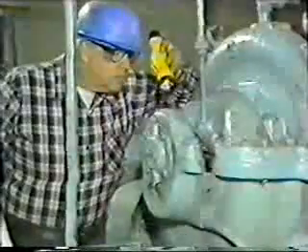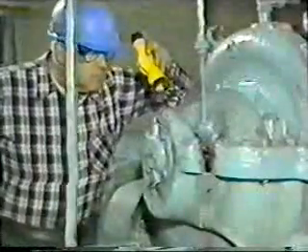Water flowing from the inside of the sleeve might indicate a problem with the sleeve. That's not the case this time. Also, check the gland follower. If the packing is fully compressed, the pump should be repacked, but ours is not.